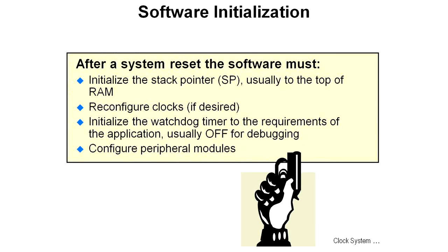So after the device comes up from system reset, your software has to initialize the stack pointer, which is usually to the top of RAM, reconfigure the clocks if it's desired, and it's almost always desired, initialize the watchdog timer to the requirements of your application. In the case of working with the part and debugging, that usually means off, and then configure any of the peripheral modules that you want to use in your application.